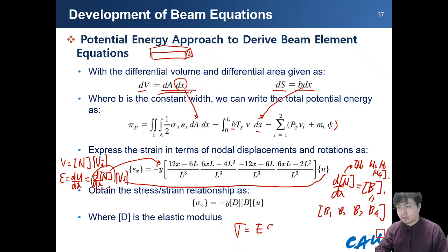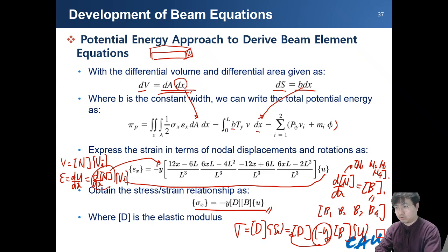And the stress is Young's modulus times strain. Sometimes we can say that this looks like this, and the strain, in the previous slide, can be expressed as minus y times the B matrices and the displacement field, and we can move the terms to the front, so finally the stress can be expressed like this.